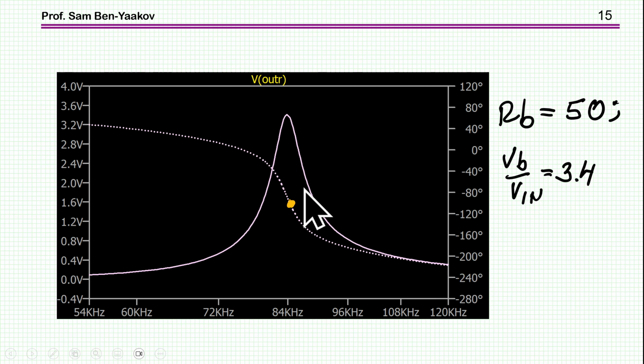Now, if we move with the frequency, then you see that the gain is changing, and also the phase is changing, which would mean that the current of the antenna will be shifted in phase with respect to the excitation, meaning that you have reactive power. You would like to have a little bit of a shift, actually a lagging of the current, to get soft switching, but of course not a large shift. Okay? So this is not actually the operating point.